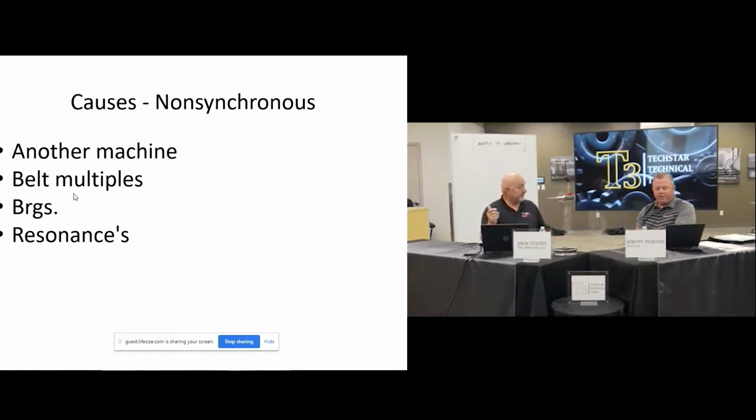And it just seems like that could really become an issue on, like we talked about, variable speed machines earlier, machines that the load changes on, things like that, that can adjust that resonance. Yes. And if you're operating that machine very close to one of its resonant frequencies for any extended period of time, your odds of a failure are much higher. Absolutely.